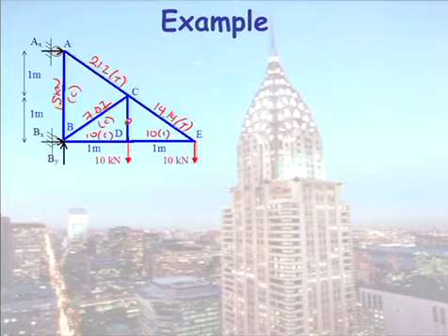Rather than tabulate the results, because your structure is not that big, I would say actually draw your structure in stick form and record the forces on it. If you want to write the tension forces in green and the compression forces in red, or highlight what's compression and what's tension with a green and a red highlighter, it's up to you. Whatever clearly shows what the forces are.